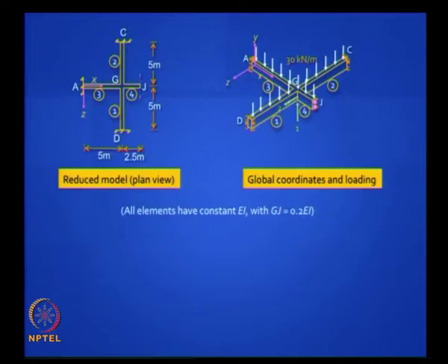If you write down the degrees of freedom, you will find that you normally would take 3 active degrees of freedom at that common joint G, but you need to take only 2, because we have just established that there is not going to be any rotation along the axis AJ, along the x axis, because of symmetry. Is it clear? There is no rotation about that axis, because that would mean twisting of that element at G. So you have to intelligently minimize your work by assigning coordinates carefully.